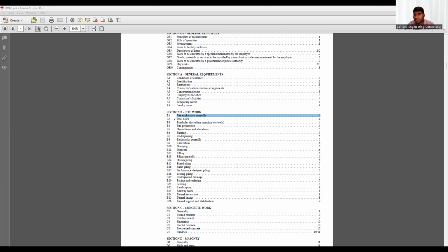For example, if you found some cables under the ground investigation, then you cannot do a machine excavation. You have to do a manual excavation by trial hole. So you excavate one place, an expected area. If you didn't find it, then you'll do another trial hole, something like that. So with these trial holes and boreholes, you get the report and everything.